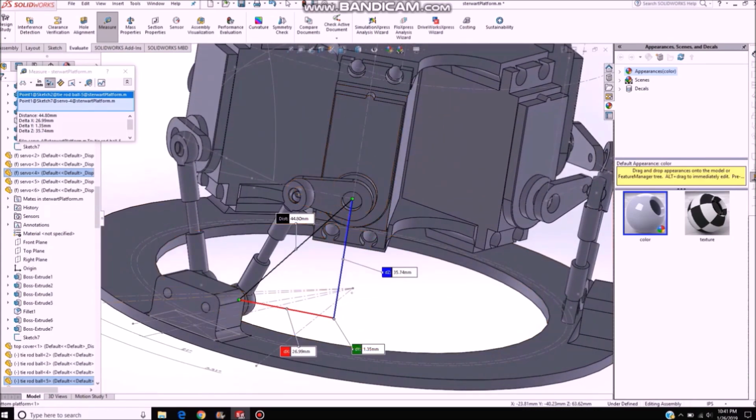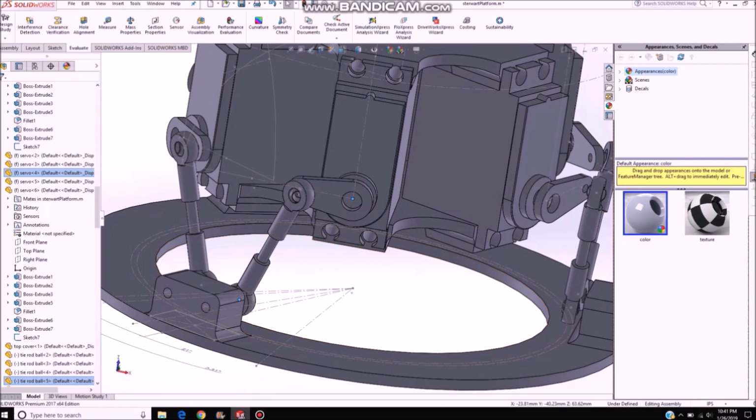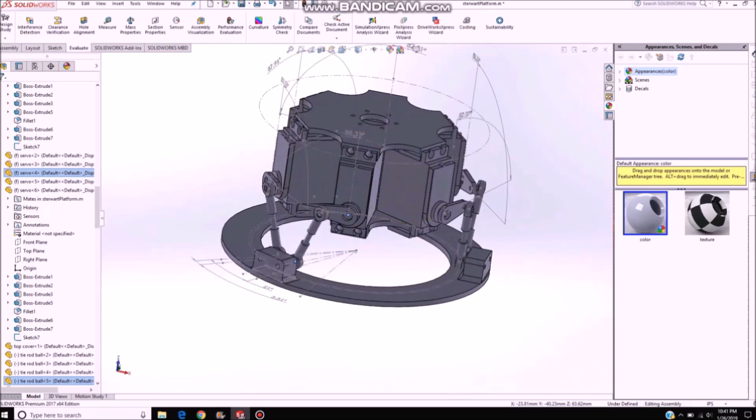So now what we need to do is back calculate those angles, right? From here to here, we have this servo horn length, and we have this length here, and from the triangle law of cosines, we can figure out that length right there. I'm going to talk more about this in code.